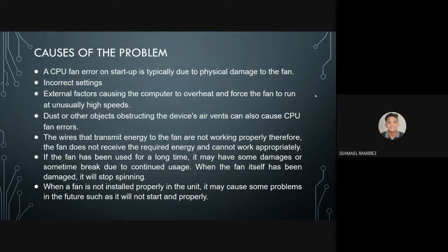The wires that transmit energy to the fan are not working properly. Therefore, the fan does not receive the required energy and cannot work appropriately. This is also related to incorrect settings or incorrect input to the fan. And if the fan does not receive its proper voltage of energy, this may prevent the fan from starting, or this can also prevent the fan from working properly.